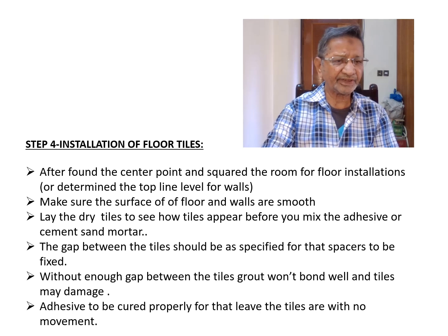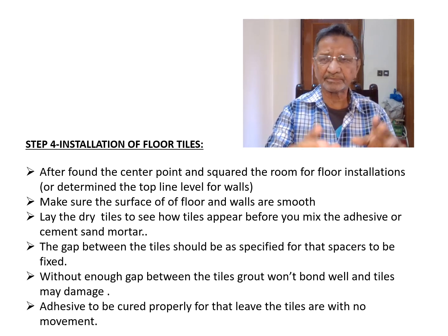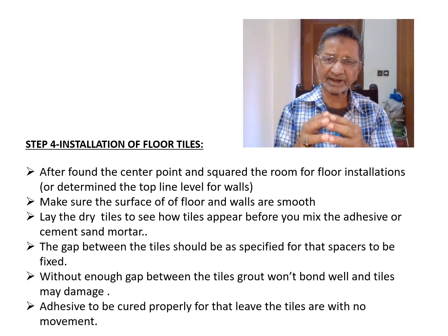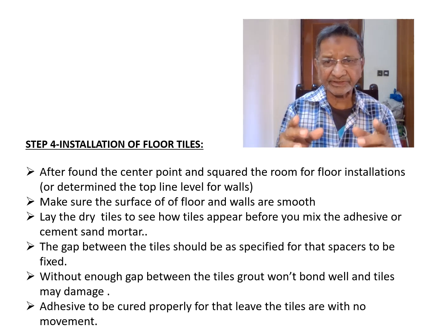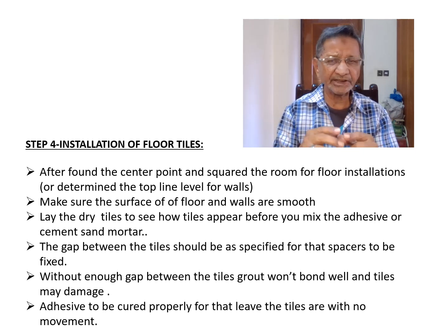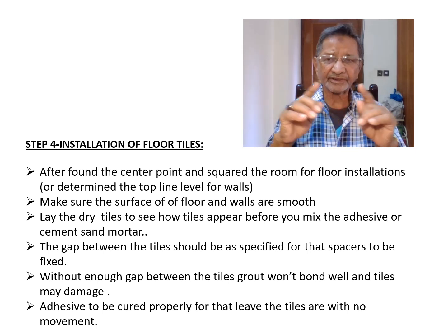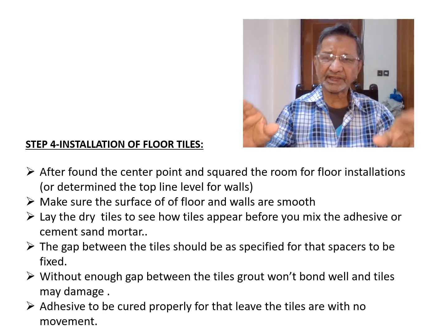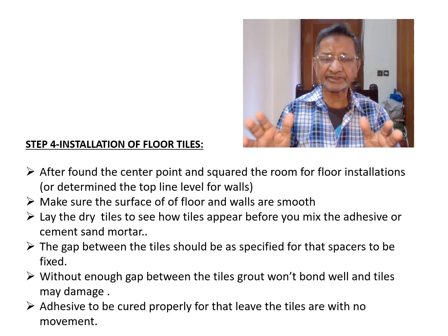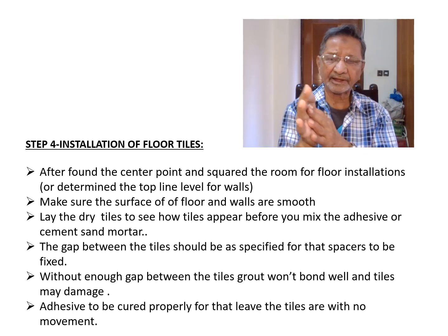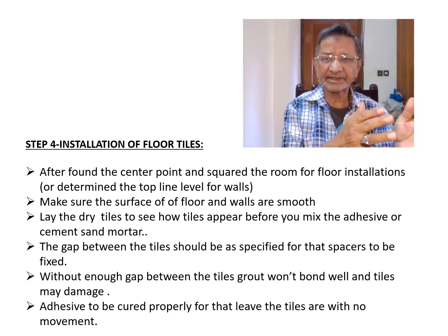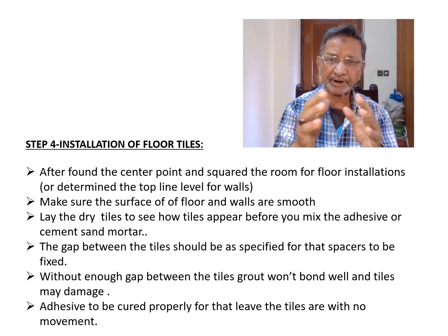Then prepare the surface. As I discussed in slide number 3, slide number 2 and slide number 1 also, especially in slide number 2, the surface should be inspected before any work is started. The surface should be smooth and leveled. Then you have to lay the dry tiles on that area and see if the pattern is okay, the tiles are laid properly, and the joints are at proper places.